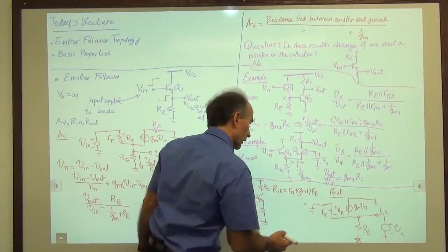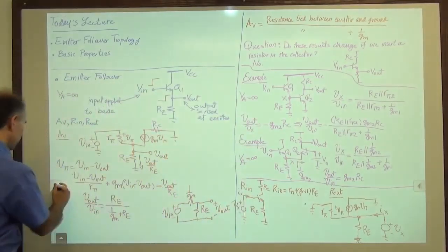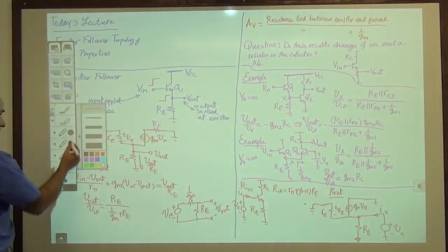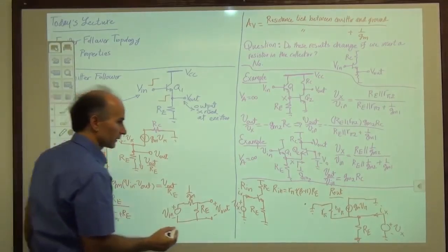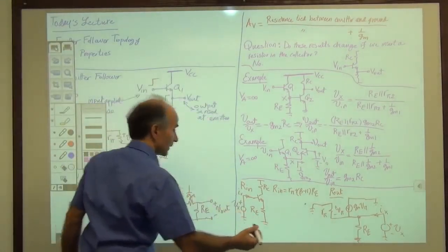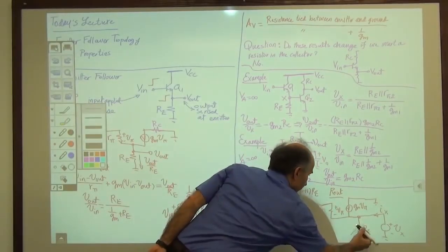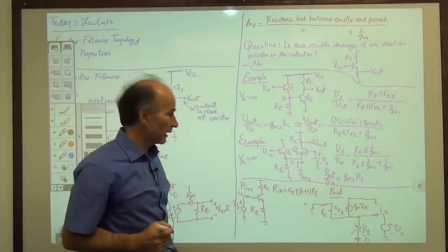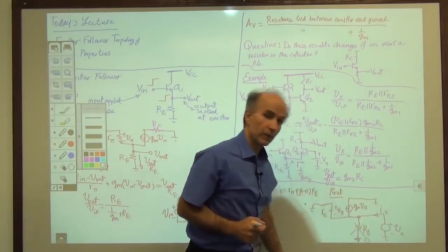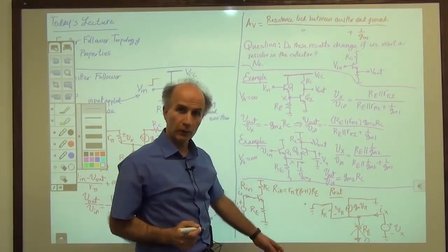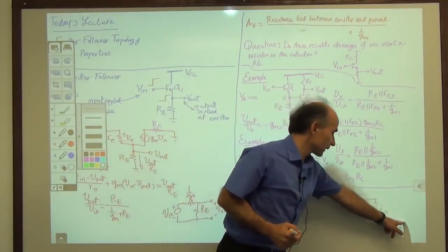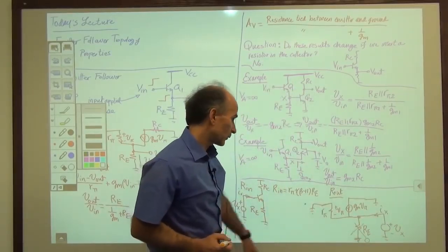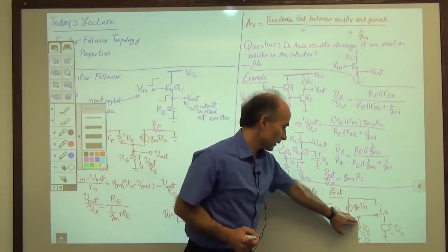So I will gently cross this resistor out. But you remember that it's there, okay? It's there, and it's simply in parallel with the voltage source. So if you don't want to do it this way, you can just draw it on this side for now, right? And we'll try to find the resistance of the rest of the circuit.